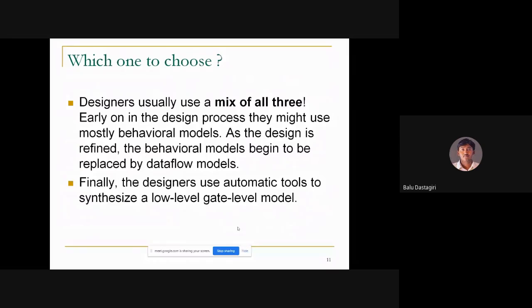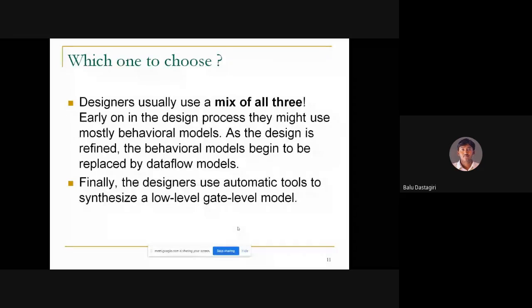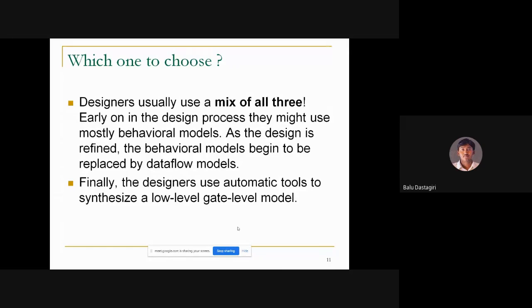Take one particular example, the ripple carry adder. If you are going for the 4-bit ripple carry adder, first you will take 4 full adders, and after taking the 4 full adders, you will describe the internal connections between these full adders. This looks like a structural program, nothing but the gate level program, where you take the full adder and define its internal structure.